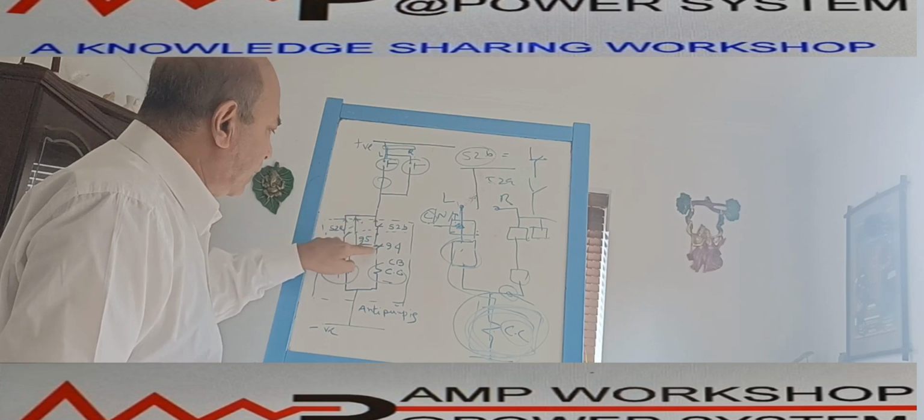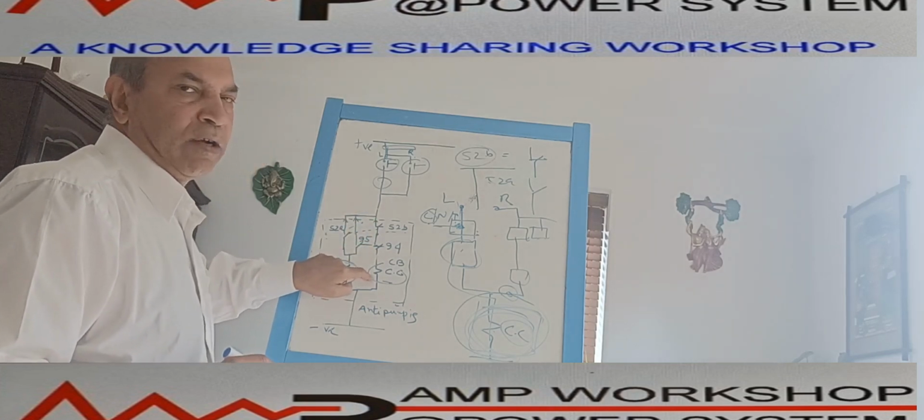One of the NC contacts of this breaker auxiliary contact is connected in series with this relay, which is called the anti-pumping relay. This anti-pumping relay has multiple auxiliary contacts. One of the NC contacts is connected in series, and that is connected with the breaker closing coil.